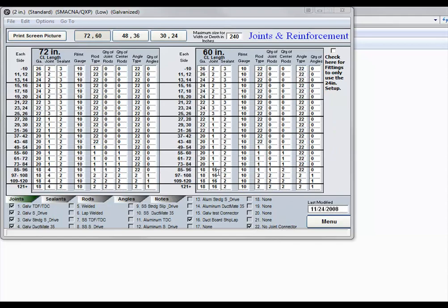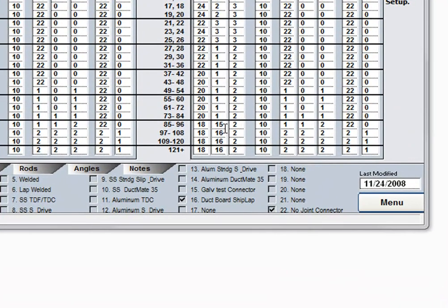So the important lesson to learn here is that if you change the location of your joint connectors, or any of the components including seams and hangers, within the data file you will have to visit all of your pressure files and modify the joint codes that are set up as the defaults, as well as the checked allowable alternates.